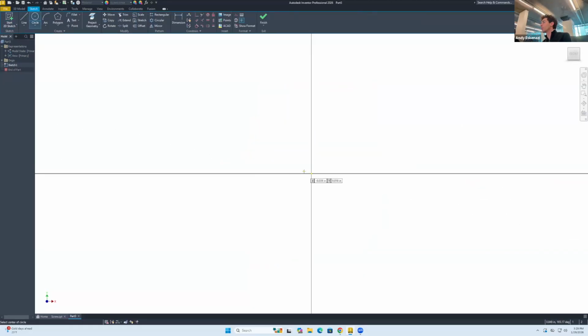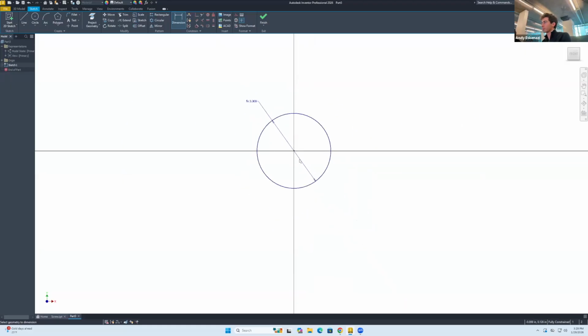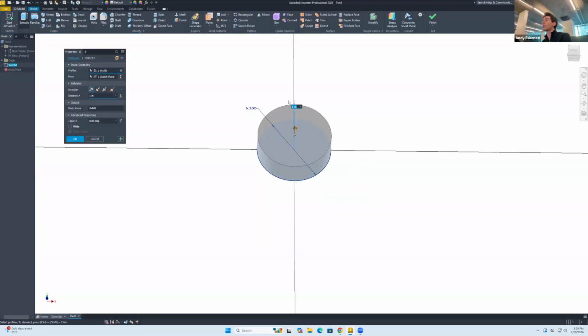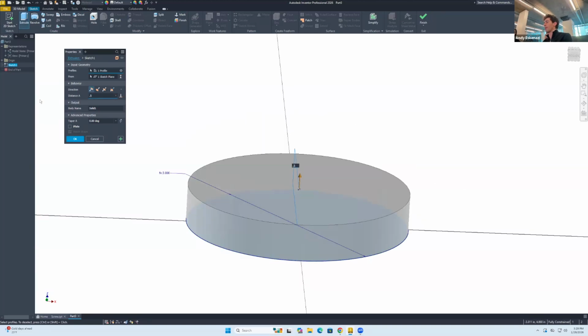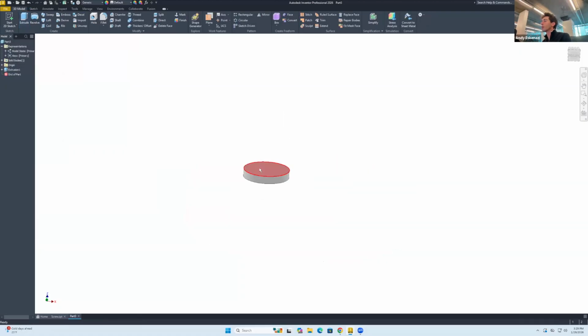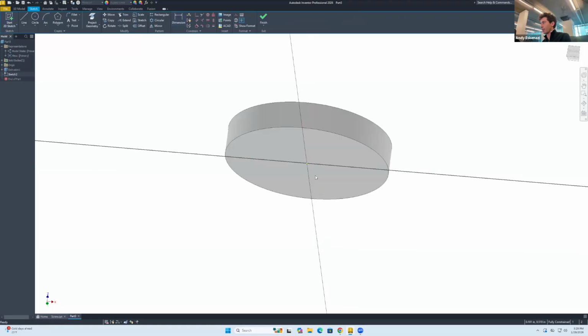Maybe what I'll start by doing is I'll build it from the seat itself first, and then we can come down. So we'll go here, and I click on D to define the space, and that can be right there. Okay, and then we go here to 3D model, extrude. We can say 0.5, so we can always have this as fixed, and then we can modify the height as we go. Then we can add fillets and all of the good stuff later.